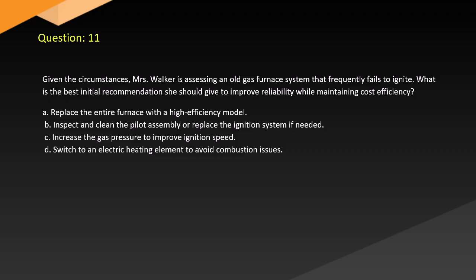Question 11. Given the circumstances, Mrs. Walker is assessing an old gas furnace system that frequently fails to ignite. What is the best initial recommendation she should give to improve reliability while maintaining cost efficiency? A. Replace the entire furnace with a high-efficiency model. B. Inspect and clean the pilot assembly or replace the ignition system if needed. C. Increase the gas pressure to improve ignition speed. D. Switch to an electric heating element to avoid combustion issues.